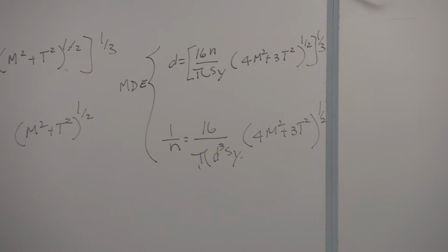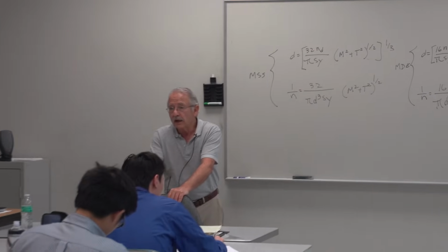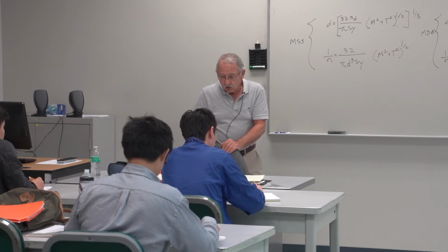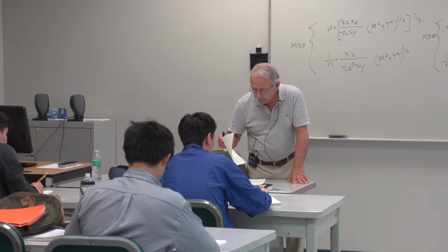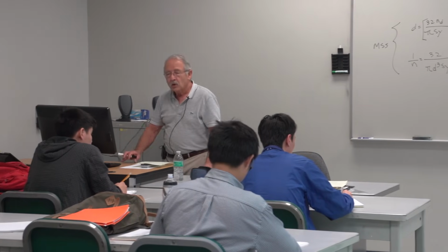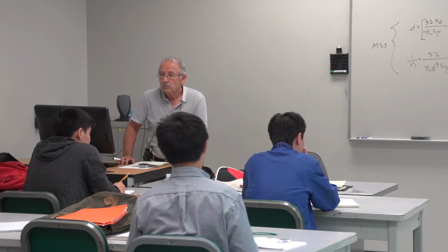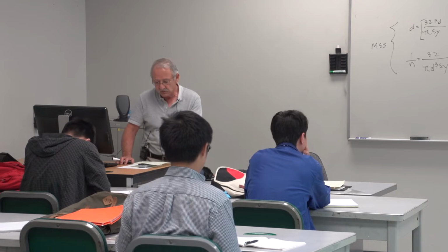Now, that is if you have no varying loads. In most cases, that of course is not true. And we have shafts rotating and or moments and torques varying. So in general, we will assume that the bending moment changes and is not necessarily completely reversed, which is the case in most shafts, but not necessarily.